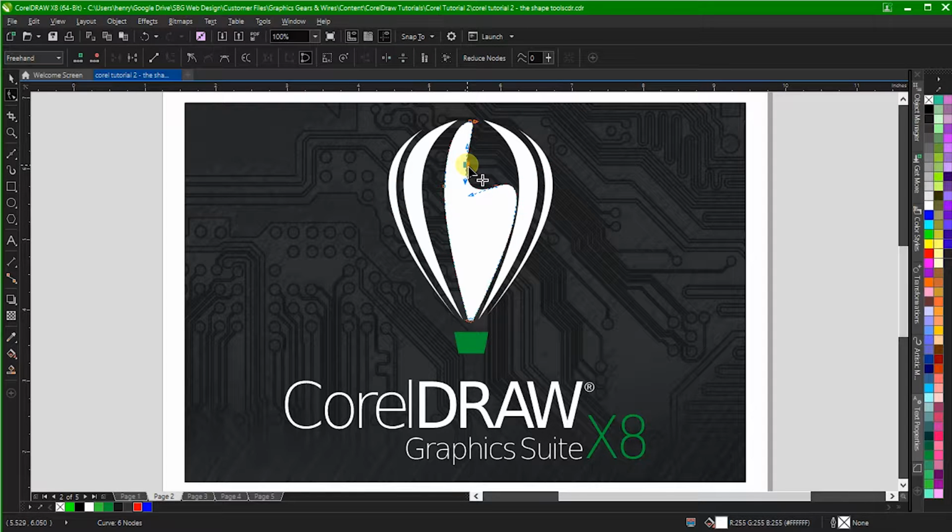Create a node by double-clicking an object's outline with the shape tool. You can also add a node by clicking an outline to select it, and then clicking the Add Node button here. You can delete a node by double-clicking it, or by selecting one or more nodes and either pressing the Delete key or using the Delete Node button on the toolbar.